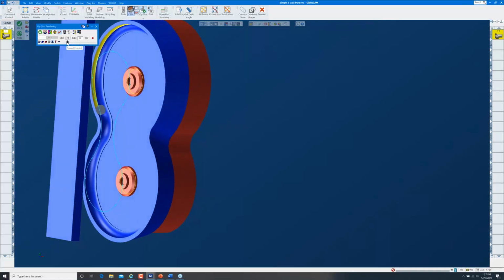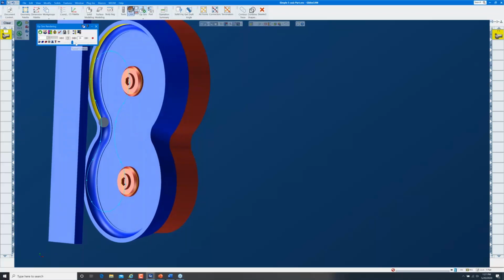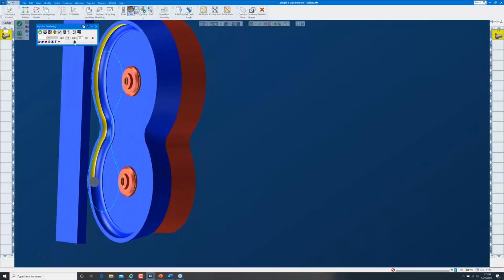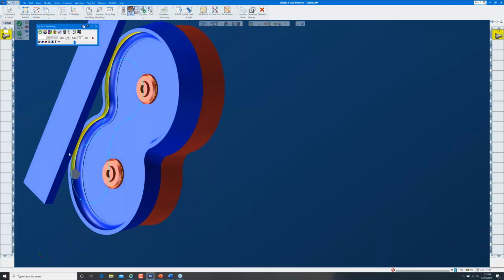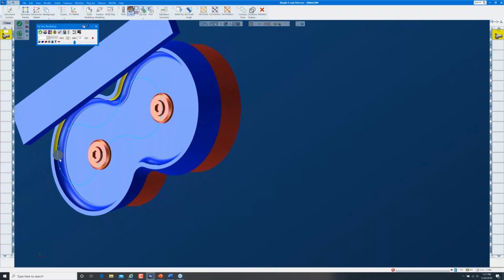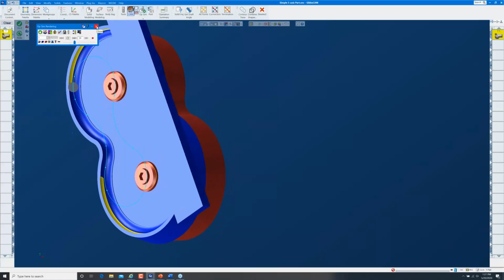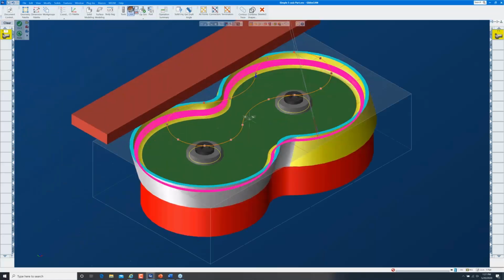It moves until it's completely off the tilt curve, and then it comes back on, but it never quite makes it centered up on it, and it tilts back off over on this side. And then as we come on around, away from the interference, the tool lines back up with the tilt curve. So I showed you that just to emphasize that it's not an abrupt change. It's a very smooth transition. As it detects the approaching gouge, it starts making adjustments for that ahead of time.